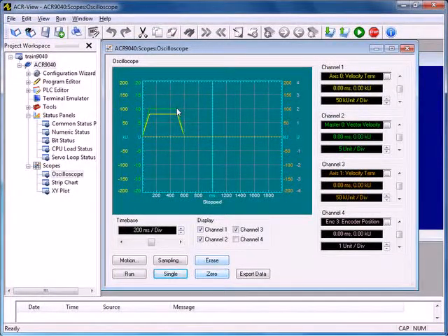So you can see this comes out to be 10 millimeters per second. Channel 1, the velocity term, is in terms of encoder counts. So since only my x-axis is moving, 10 revs per second times 8,000 counts per rev, since I have a BE motor with a J encoder, that's 8,000 counts post-quad encoder, that works out to be 80,000 counts. So I've set my scaling to 50,000 units per division on there, and you can see they both accelerate and stop at the same time, and the total time for the move is around 600 milliseconds.